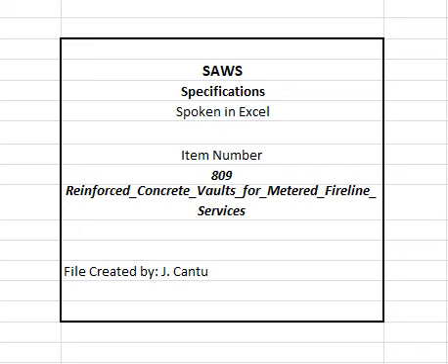4. Make, cure, and test specimens in accordance with ASTM-C 31 and ASTM-C 39. 5. When taking compression test specimens, test each sample for slump according to ASTM-C 143, for temperature according to ASTM-C 1064, for air content according to ASTM-C 231, and for unit weight according to ASTM-C 138.